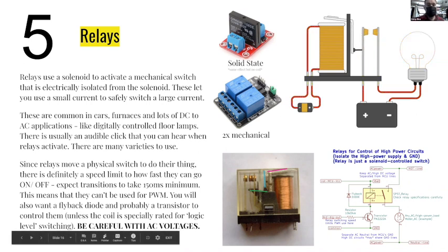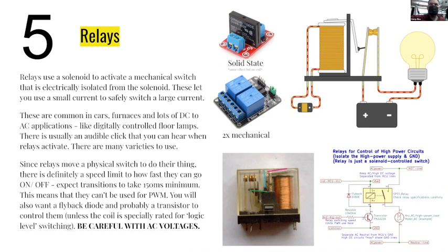But relays like this totally work. Like the old controllers in an old car, they would have little digital or analog electronic control systems. And then a relay would be what tips on the starter motor, right? They don't want the control electronics to be actually pushing energy from the car battery to the starter motor, because it takes a lot. It starts stalled, so it takes the most current to get it started. So they'd use a relay to go from the control electronics to the starter motor direct from the battery in order to make that happen.